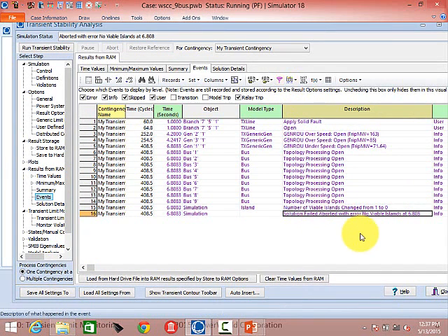That wasn't the power flow network power balance not working. That error comes when you no longer have any viable islands. You no longer have any islands with generation. So whenever there's topology changes, where you see topology processing open, it's going to check to see how many viable islands we have, and we have criteria in there for what's a viable island.